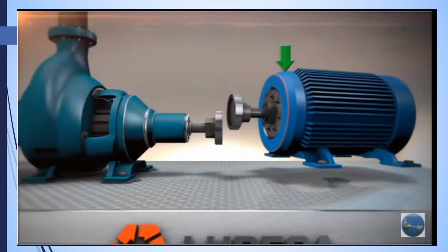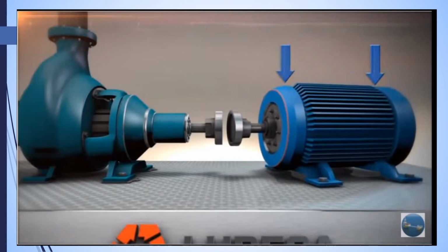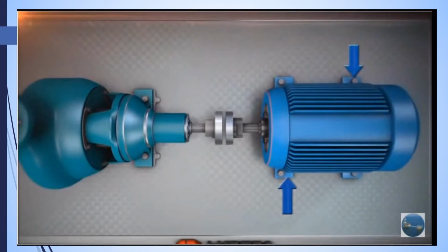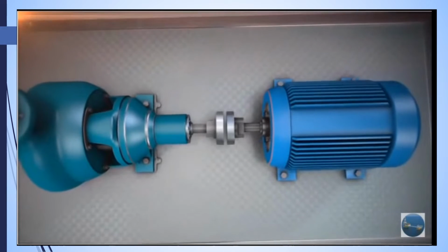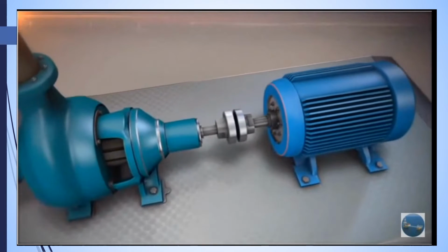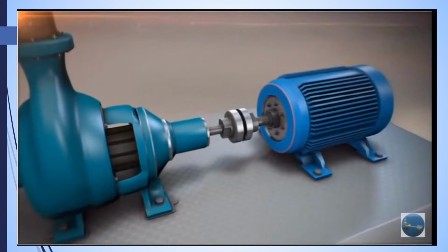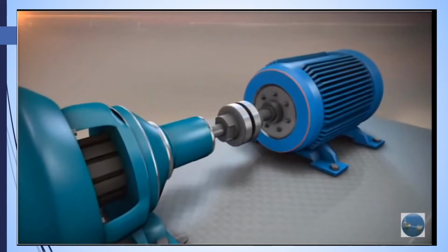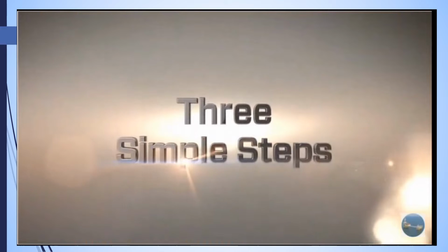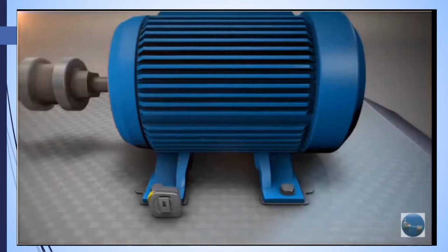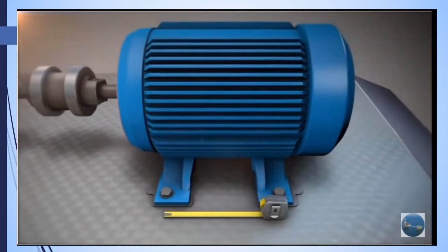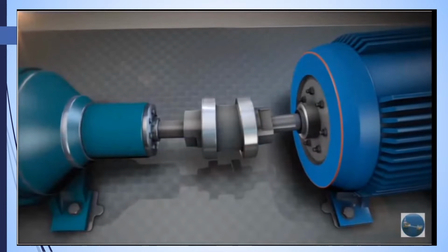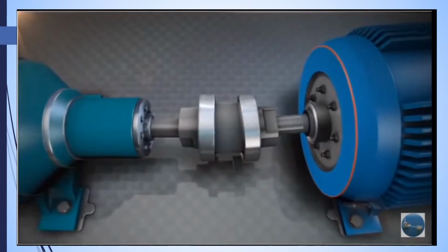Once we know the misalignment, we can correct it by adjusting the movable machine vertically and moving it side to side in the horizontal plane. If we get the two rotational center lines to be nearly within tolerances in these two directions or planes, then they will be nearly collinear and therefore properly aligned. The process of precision alignment can be broken down into three simple steps. First, measuring and inputting the machine dimensions. Second, measuring the misalignment between the shaft center lines of rotation. And finally, calculating the necessary corrections and aligning the machine to be moved.